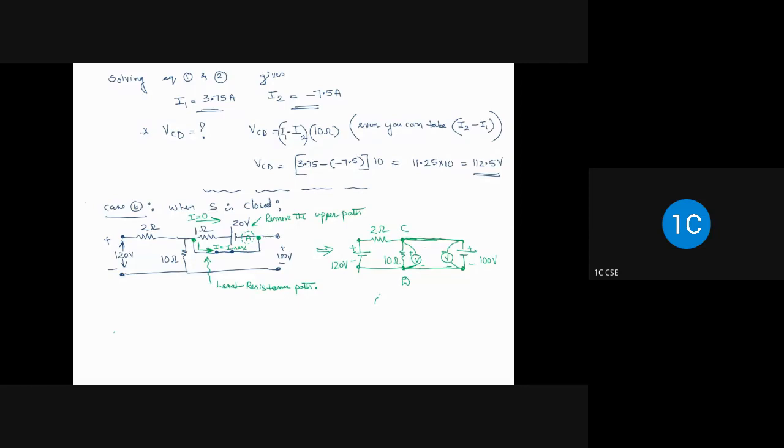Connecting the voltmeter across C: 100. Yeah. Or connecting the voltmeter across, let's say, EF is the same, because potential of C is equal to potential of E, because there is no resistor connected in between. Similarly, potential at D is equal to potential at F. So directly you can write VCD is equal to 100 volt.